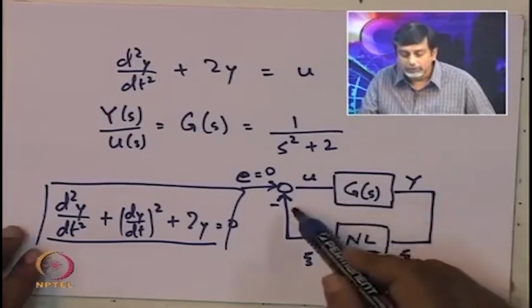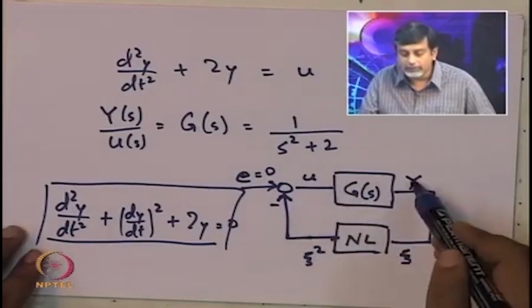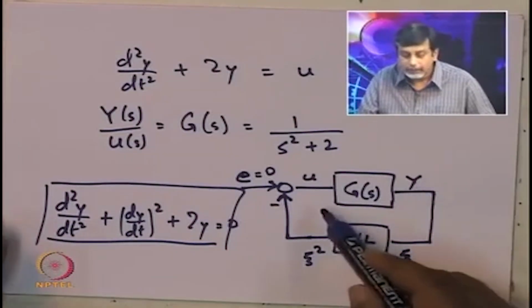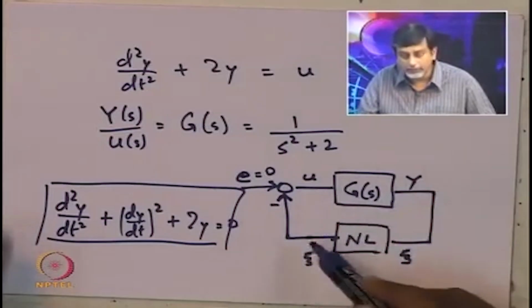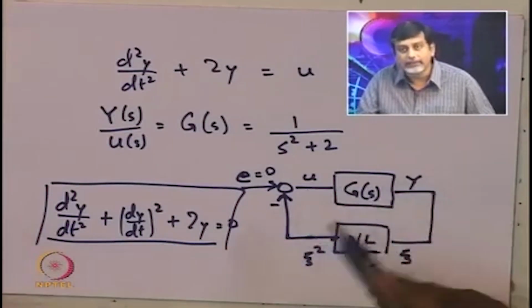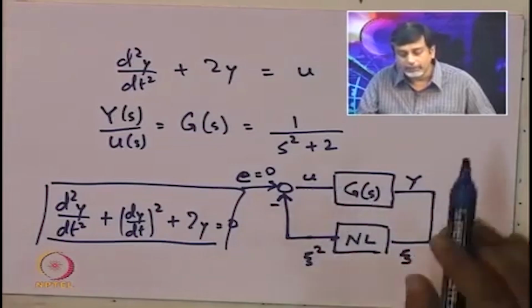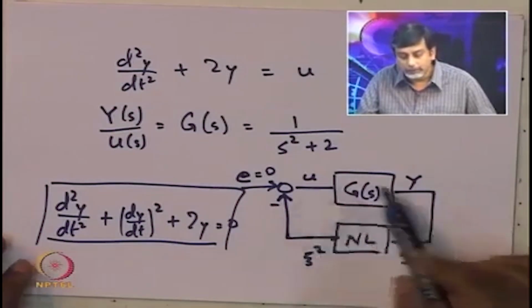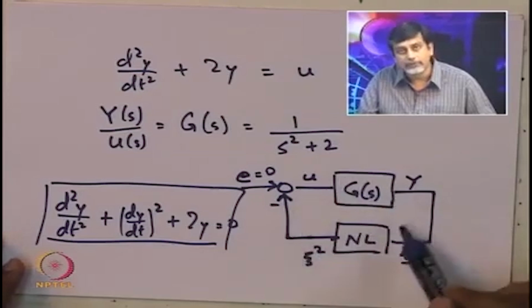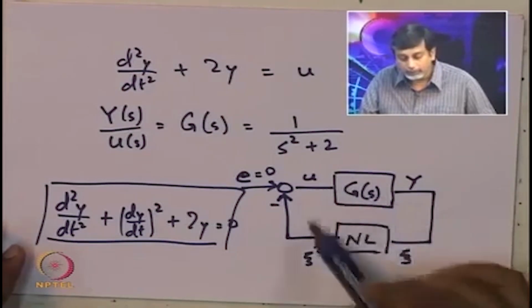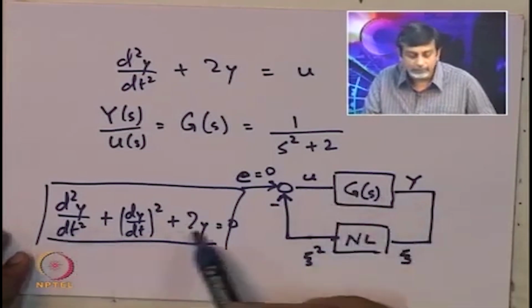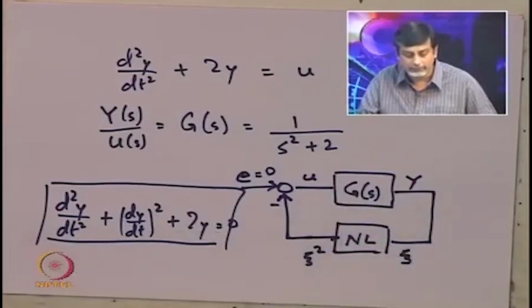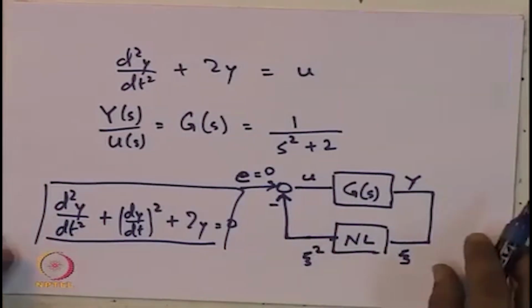So, if you set up this feedback system and set y with some value, and then you let this system evolve, and if this system evolves finally settling down to the value y equal to 0, u equal to 0, then that would mean this system is asymptotically stable, and that effectively means that the original nonlinear system is stable. Now, once this clever trick was discovered, it was used again and again.